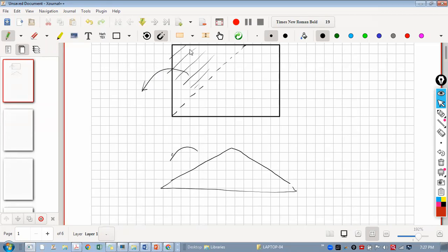That means whenever it tries to fall down, definitely, if you provide a retaining wall over here, it will exert a pressure. So why do we provide a retaining wall? To retain this soil. And this soil is trying to fall down, and that's why it will apply a pressure on the wall. Generally, that pressure is triangular in nature. So this wedge of the soil will try to fall and will exert a pressure on this retaining wall. So that is the reason.